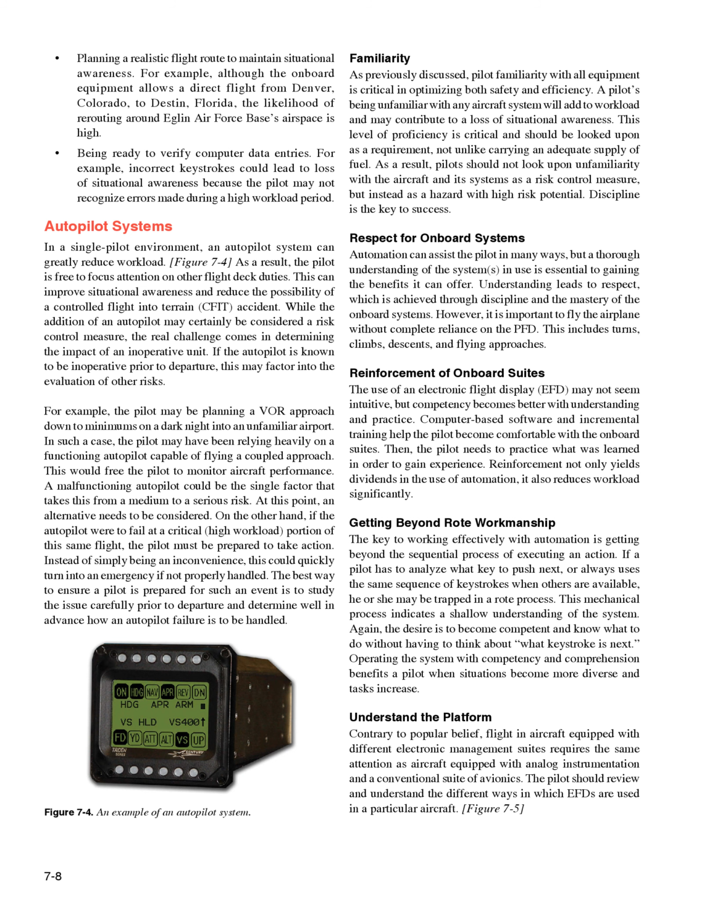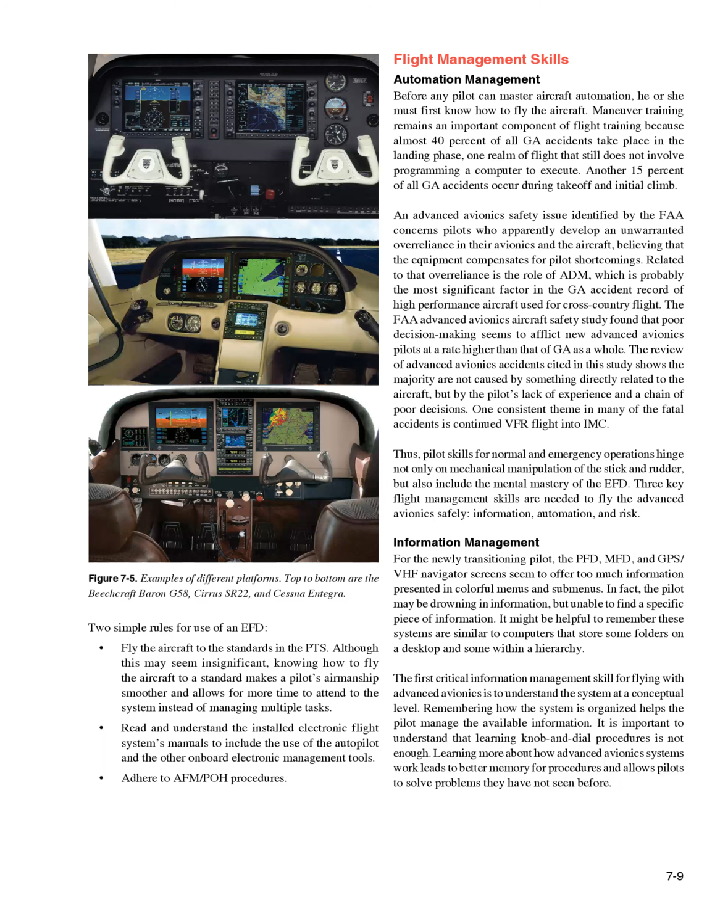Understand the platform. Contrary to popular belief, flight in aircraft equipped with different electronic management suites requires the same attention as aircraft equipped with analog instrumentation and a conventional suite of avionics. The pilot should review and understand the different ways in which EFDs are used in a particular aircraft. Figure 7.5. Two simple rules for use of an EFD.